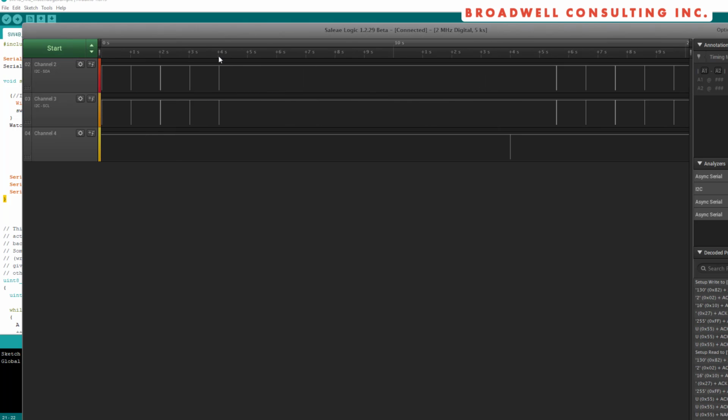If we take a look at the duration, we see that it's quite nearly exactly 10 seconds from the time of the last transmission until the Serial Wombat pulls the reset pin, after which there's a couple of seconds worth of boot up time for the Arduino. Then we start iterating through, doing the divisions and resetting the Serial Wombat Watchdog.